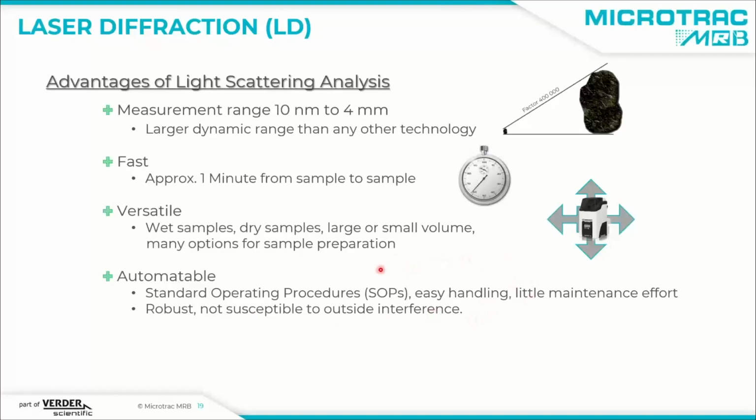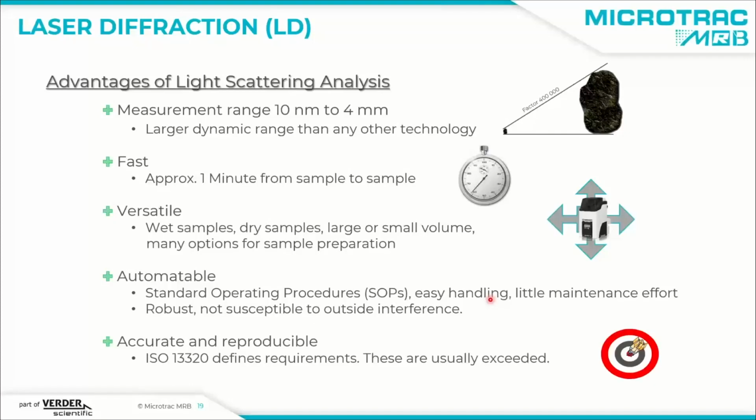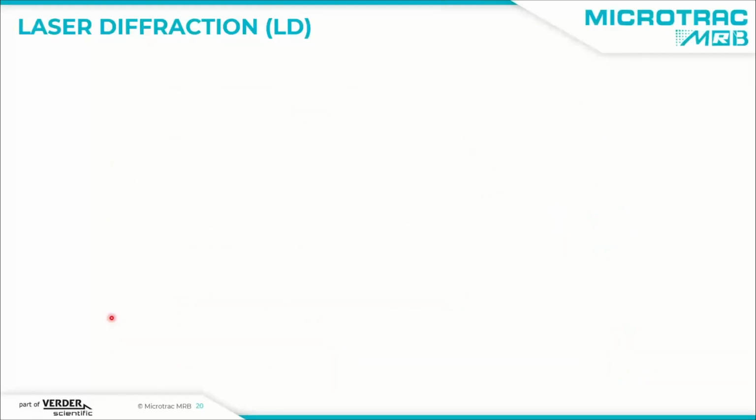Also, the handling can be done by staff that only received a minimum training. So it's really push the button, add sample, and look at the result. And as we've seen, it's very reproducible and also very accurate. If you want to know more about laser diffraction, read the ISO 13320. There the method is described in great detail, and it also defines the requirements for an instrument in terms of accuracy and reproducibility.